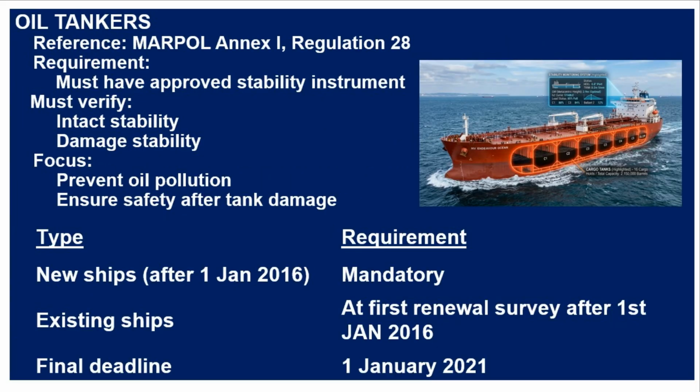MARPOL Annex 1, the IBC Code, and the IGC Code have been amended by IMO resolutions respectively, and require that new and existing tankers shall be fitted with an approved stability instrument capable of verifying compliance with intact and damage stability requirements. Requirements are applicable to new oil/chemical tankers constructed on or after 1 January 2016 and new gas tankers constructed on or after 1 July 2016.